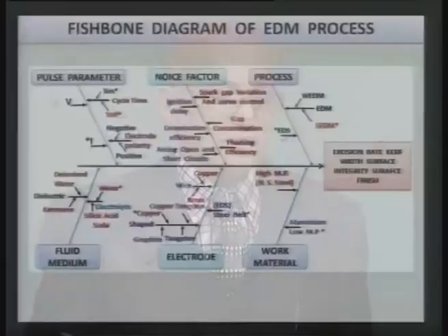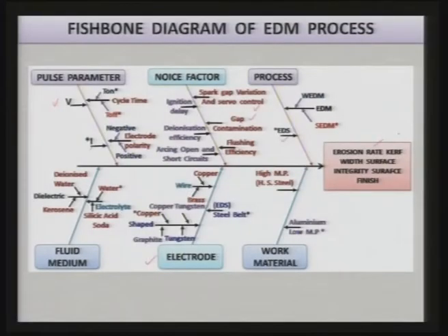Apart from that, due to the high temperature gradient in the localized area and surrounding area, thermal residual stresses are created in the machine component. That is another point which one should take into consideration while evaluating the performance of the EDM process. So, this diagram shows us the various important parameters in the EDM and wire EDM process, and they are also the parameters with the help of which you can evaluate the performance of the EDM process.